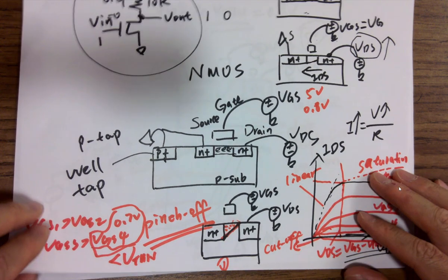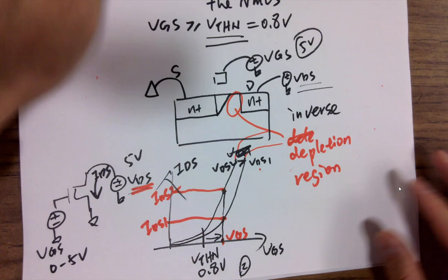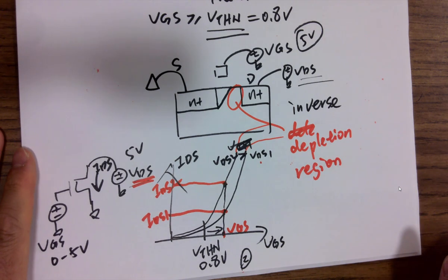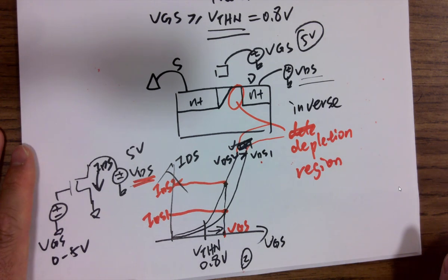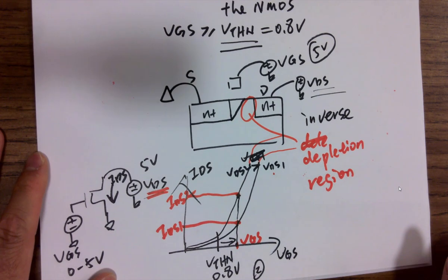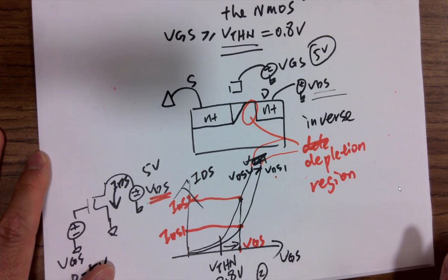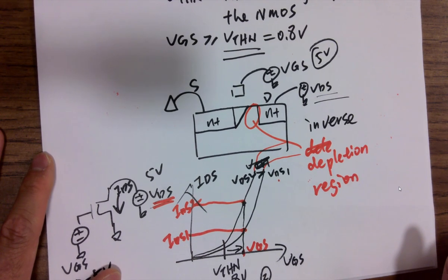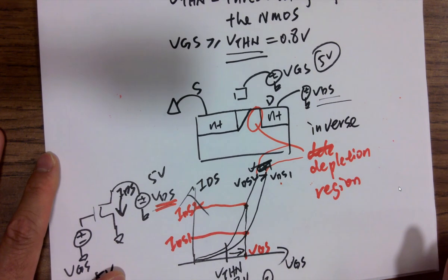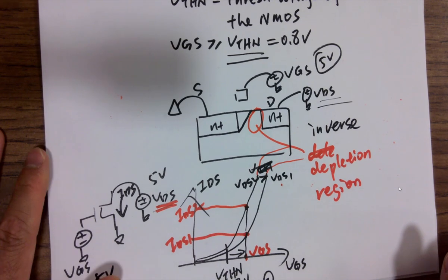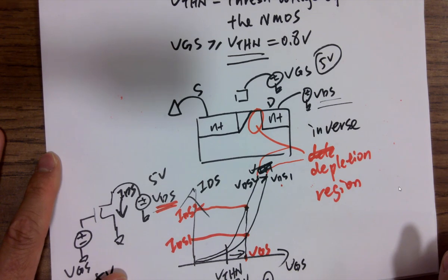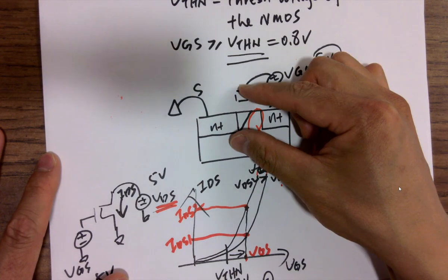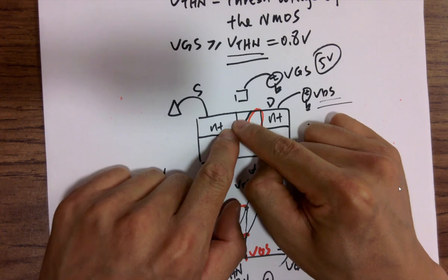On the other graph, when you increase the gate to source voltage, is that kind of pushing the channel back open, so that you drew the pinch off of the channel in between the N plus regions? Is it just pushing it back down? Yeah, so it's actually attracting.